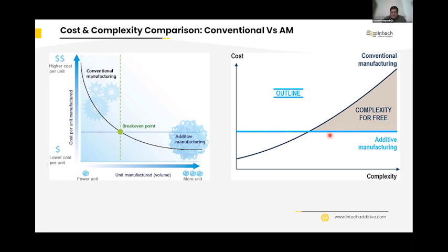Primarily, this could be the thing we can look at: why do I really need to have a nut, screw, and bolt in this geometry? Can I make it integrated? Can I make it complex? And if I can really manufacture them, then 3D printing is the answer. And what volume am I looking at? If my volumes are in lakhs, well, I better reduce the complexity. I still go ahead and make several pieces and glue or join them together. So it's a good decision-making slide.